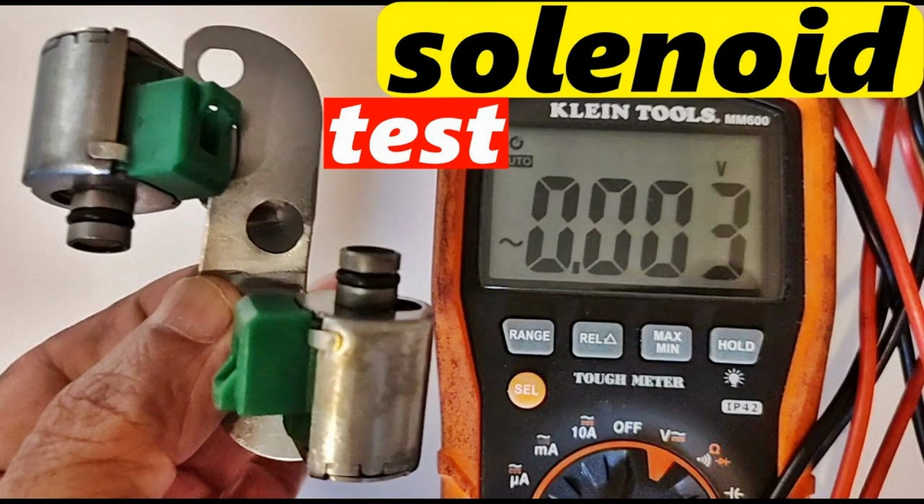Not all components of the automatic transmission oil system can be repaired. Therefore, it is recommended to find out in advance which solenoids are used in the vehicle and whether their construction is disassembled. The vast majority of modern solenoids are non-disassembling. Restoration of their performance is possible only with the help of purging or ultrasonic action.